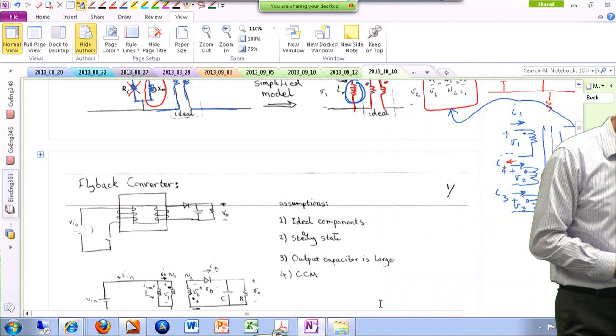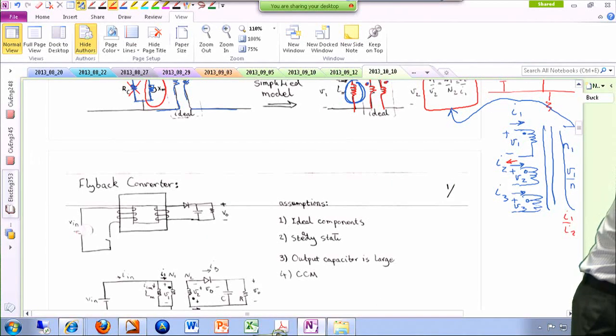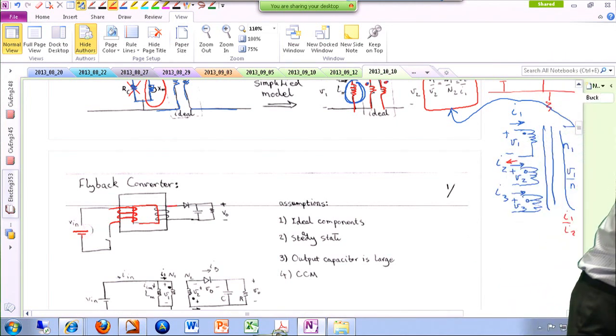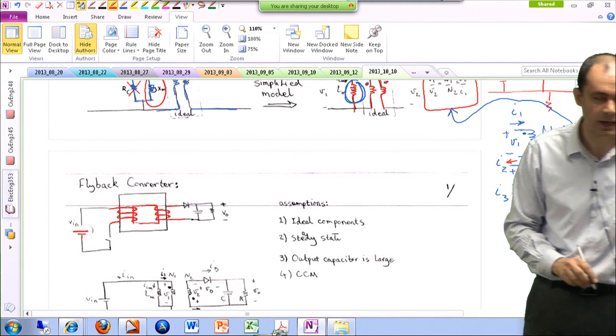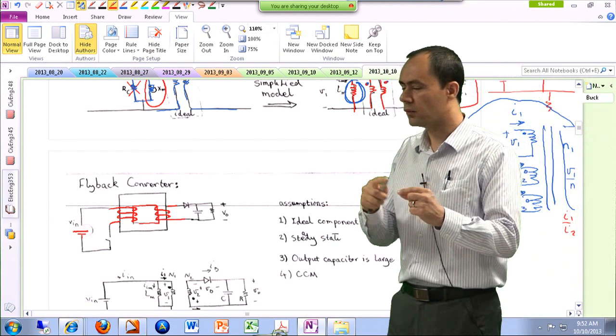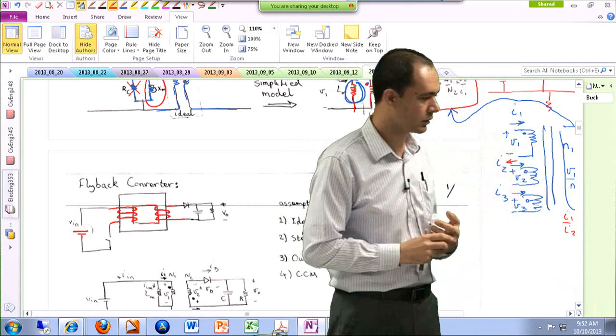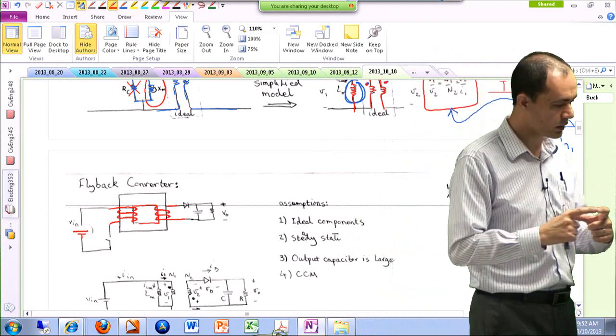All right. So here is the circuit diagram. You have this transformer or coupled inductor, and the windings are like this. The direction of these windings is important. On paper it doesn't matter, but if you try to build it, where you place these dots depends on how these windings are actually wound around the core. But anyway, you have this coupled inductor.